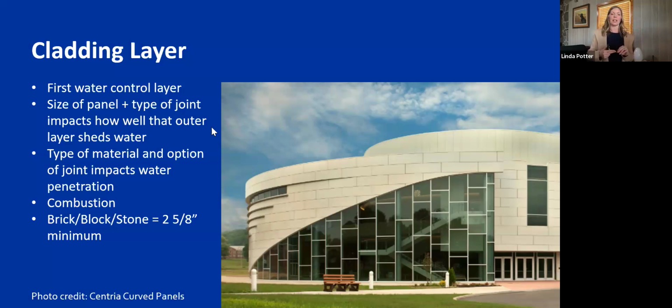The other thing that's interesting is that if you were using your masonry code, how you know to build these brick walls, there are standards here. The masonry unit itself has to be at least 2 5/8 thick in order to be anchored appropriately to the backing, to get the proper embedment of that anchor, to keep that laterally connected so that it doesn't fall off the wall. There's none of those things established today. You can have those as long as you can connect it, as long as the company is fabricating it. Like there's a way to connect it, but there isn't an industry standard that tells us this is how we approach that.